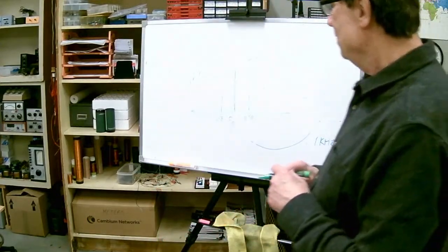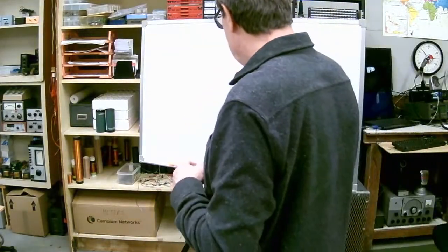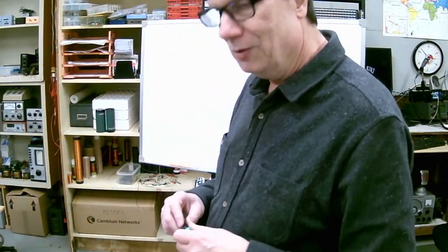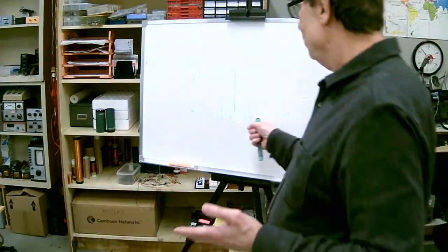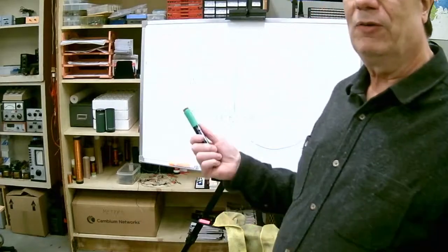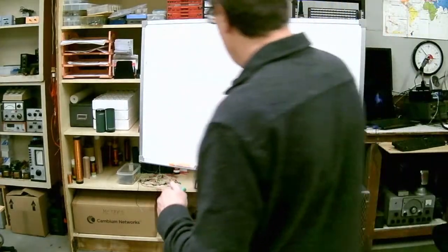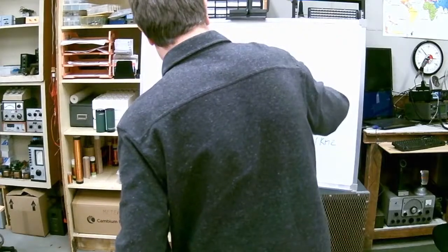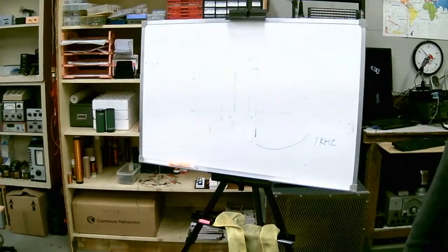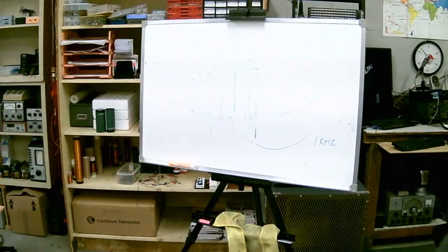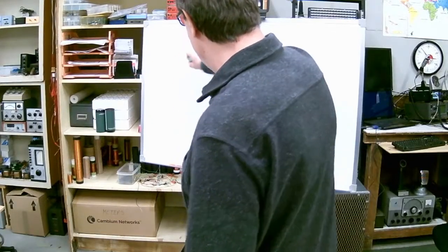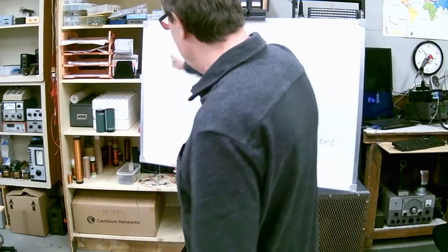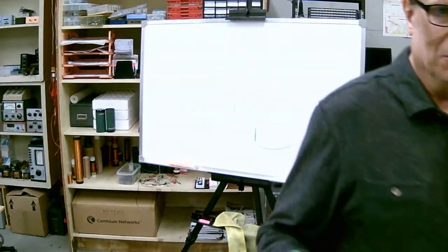So we have these three signals there, and when you either modulate or demodulate them, you need them all together. Now, in order to transmit this, your transmitter has to be able to accommodate all of that. That's your total occupied bandwidth. So if you're transmitting 10 kilohertz audio, you're going to have sidebands up at 10 kilohertz, so you have to accommodate twice that, up and down 10 kilohertz. Your bandwidth has to be 20 kilohertz wide.